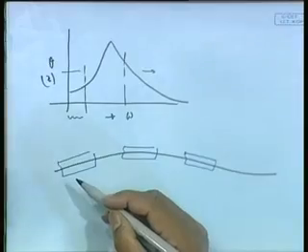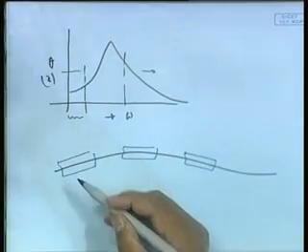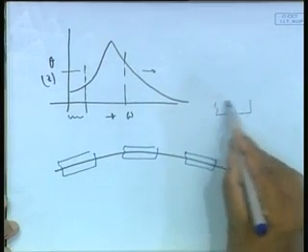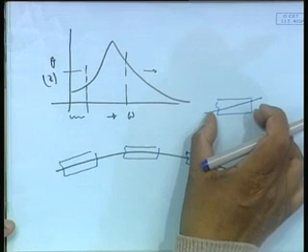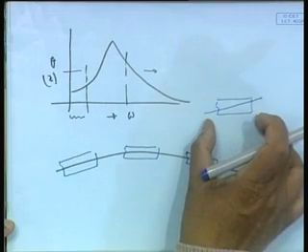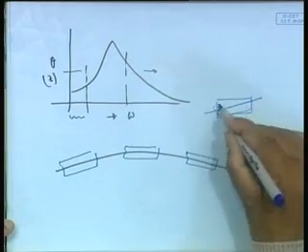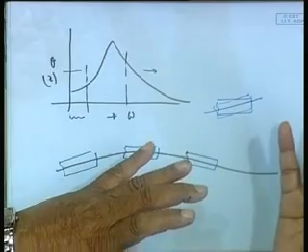See, it is a very small frequency, which means a long time. So I have enough time. When the water wave has a shape like that, there is enough time for the hydrostatics to balance itself and make the body aligned, because this aligned position is where my hydrostatic force exactly balances.